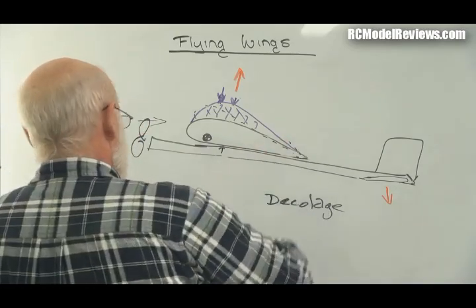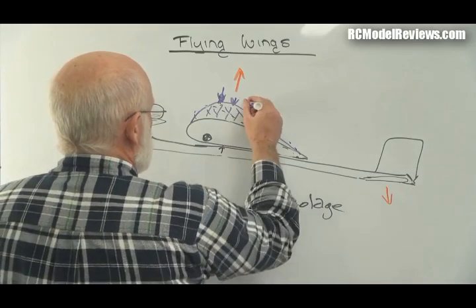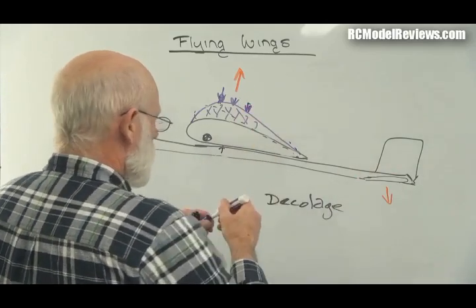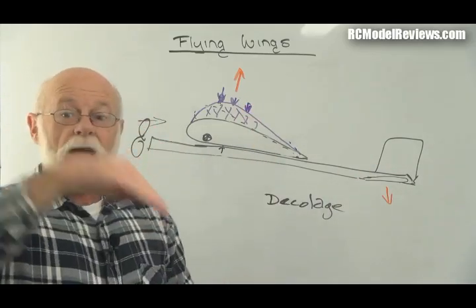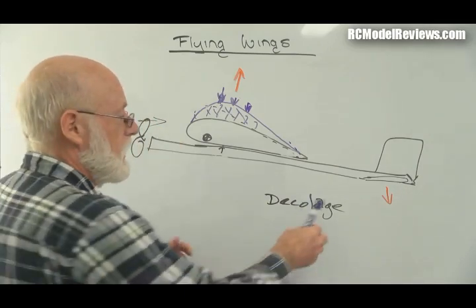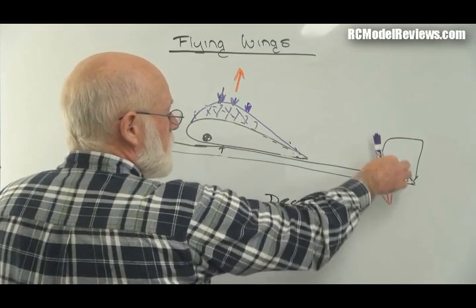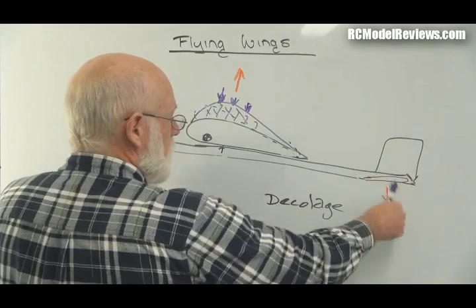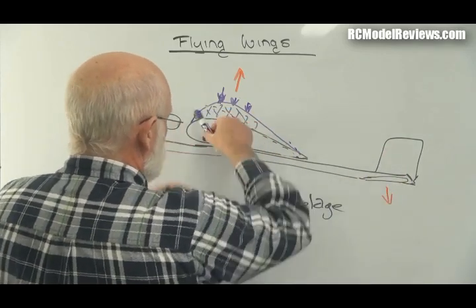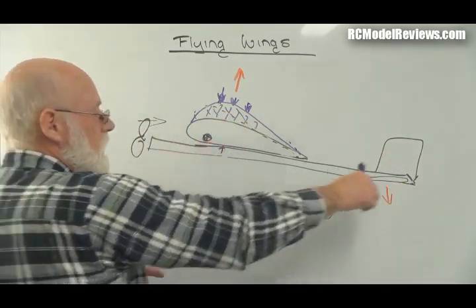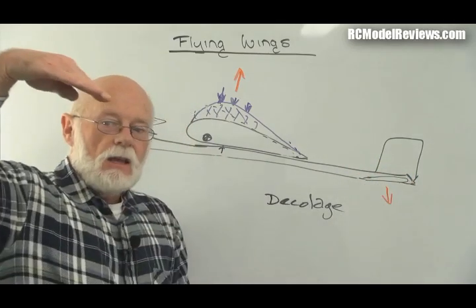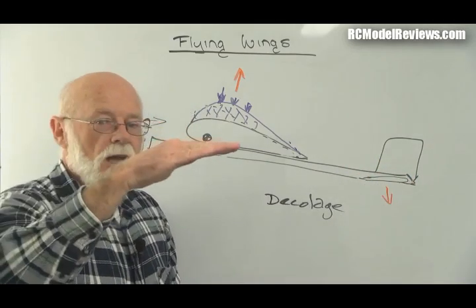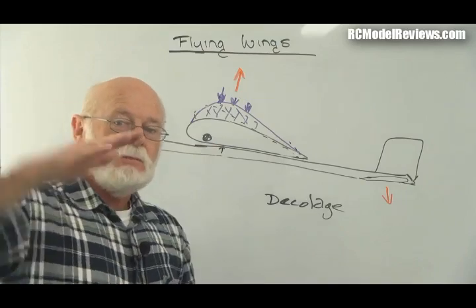When the aircraft noses down, the centre of pressure will move back, but this is really not important in this case because we have a tail. Once the aircraft noses down, it will pick up speed. And because the air over the tail is now travelling faster, the downward force on the tail, trying to push the nose up by pivoting around the CG, will increase. So the aircraft will go faster and the tail will push down and it will level out again. That's what gives pitch stability.